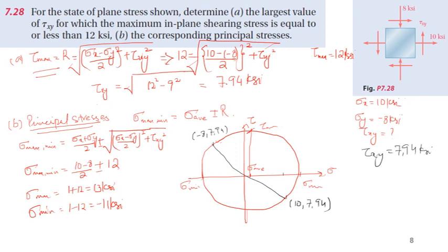And if you draw a line, this is representing our state of stresses given over there. These are my principal stresses, sigma maximum and sigma minimum, and the maximum shear stress is tau max. And graphically we could present those stresses, and this is known as the Mohr circle for plane stress.